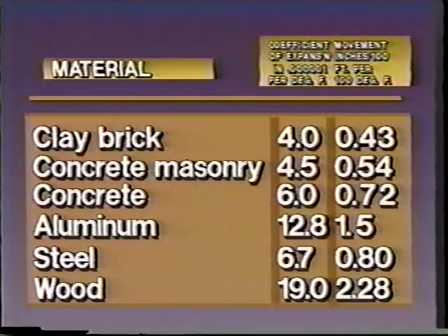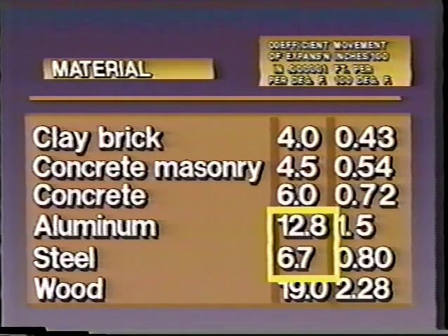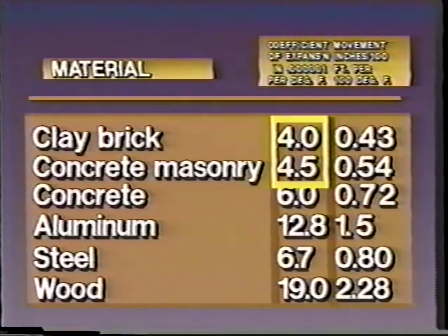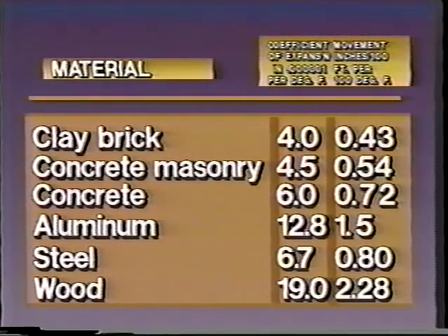As you know, materials will increase in size when heated, and metals expand at a much greater rate than brick. So, when metal is embedded into masonry, it may cause cracking. Railings embedded into the brickwork often will crack the brickwork it's attached to. The brick also expands when heated, usually about 1/2 inch in 100 feet.